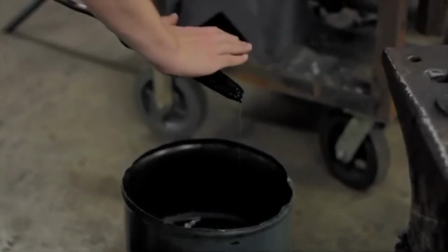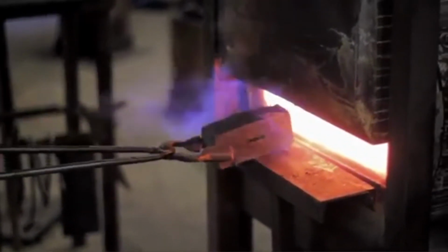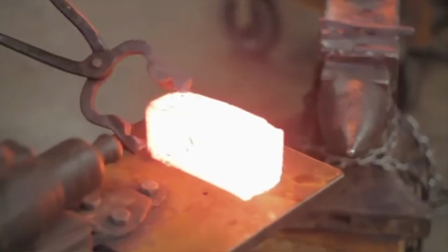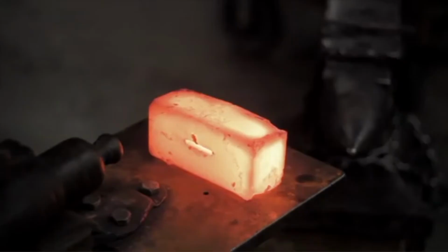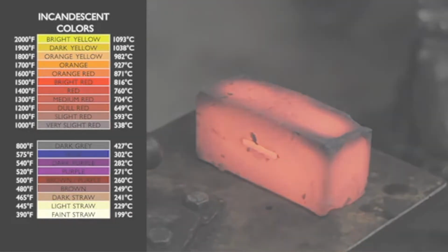This process is followed by tempering, which takes far longer. Multiple rounds of tempering might be required to achieve the optimal properties. This is typically done 2 to 4 times for high-speed steel. Each round of tempering involves holding the steel for 2 to 4 hours at a minimum temperature of 540 Celsius, which must be lower than the critical temperature. The steel must then be air cooled to surrounding temperature before the next tempering cycle.